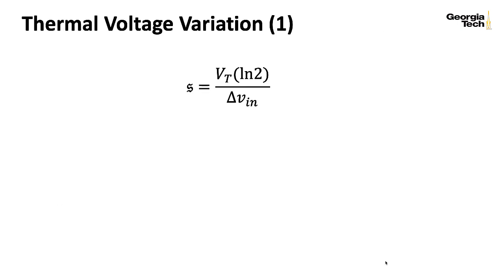Okay, so we've seen how to use a pair of transistors to combat the way the saturation current I_S changes with temperature, and we've seen how to overall set a volts per octave parameter. Now we need to deal with VT, this so-called thermal voltage. The way we've presented it so far is that we implement the scaling factor according to this ratio of resistances in the input op-amp and according to this little tweak S tilde we get from that resistor divider with the trim pot. Now, VT isn't a constant.